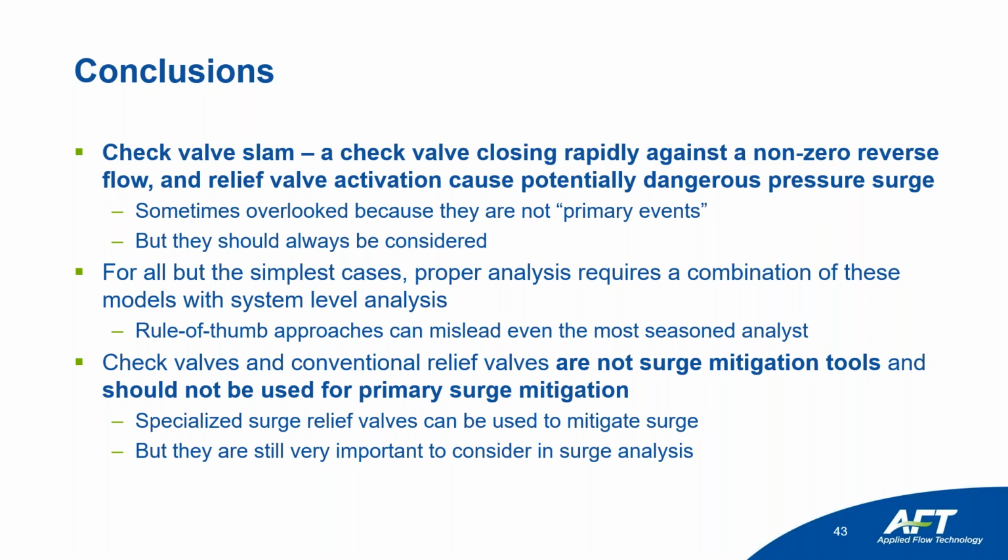But you always need to consider them whenever analyzing your system for the possibility of surge getting out of hand. For all but the simplest cases, you would want to use a system level analysis like simulation software. Impulse is one that provides that, and rule of thumb approaches aren't going to be sufficient. Using the Joukowsky equation is a good estimate, but oftentimes it can still provide you with misleading results. So we still advocate that you simulate your system to the best of your ability and use as accurate information as possible to represent your system.